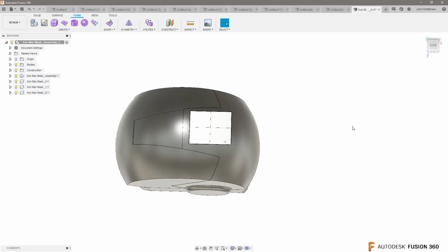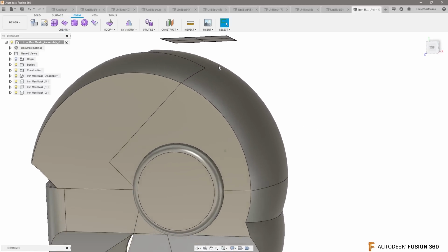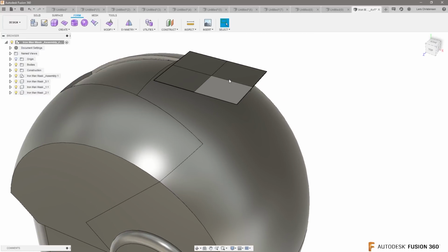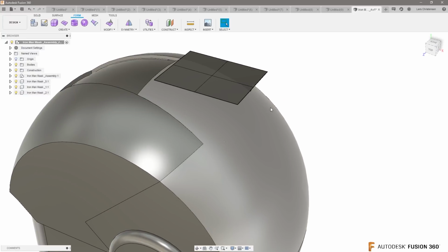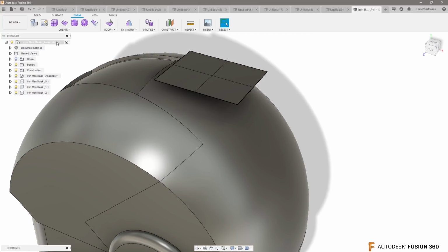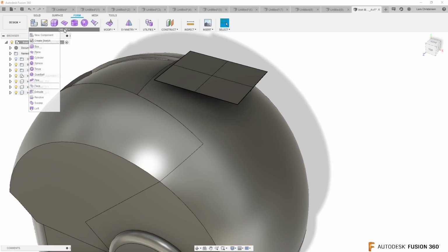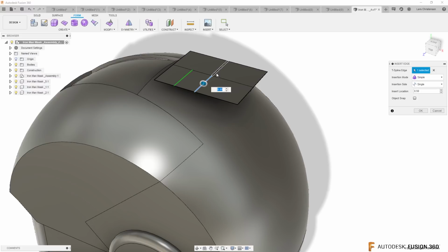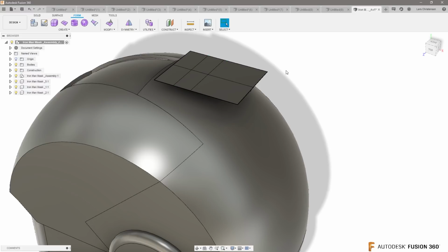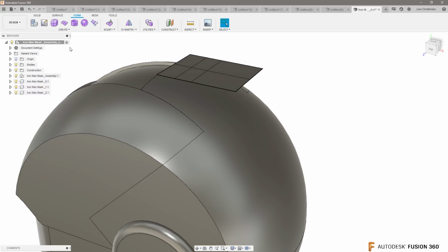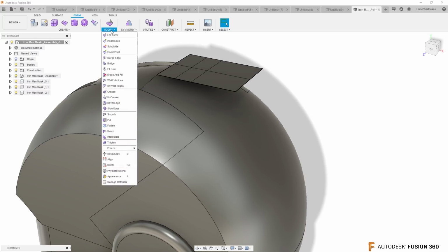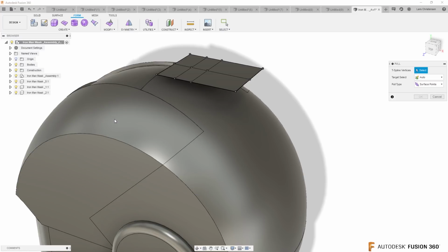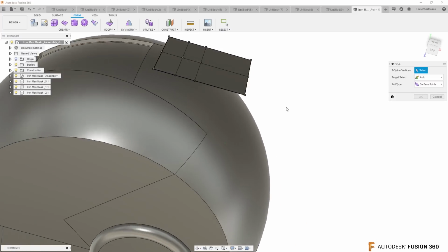Okay. So now we end up having a piece here. Now I've talked about form or sculpting before. You can make this more accurate by inserting more edges. So if you went in here and inserted more edges, this will get more accurate. But there's this cool function I've got to show you. There is in here a pull function. So if you're selecting pull, check this out.